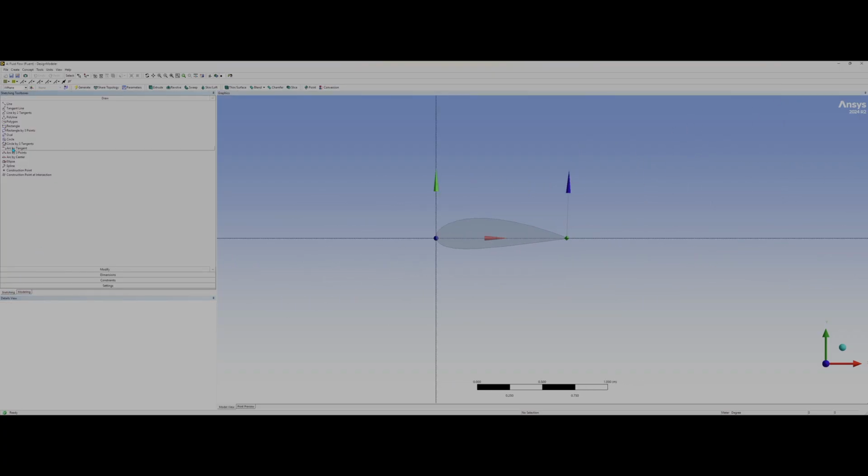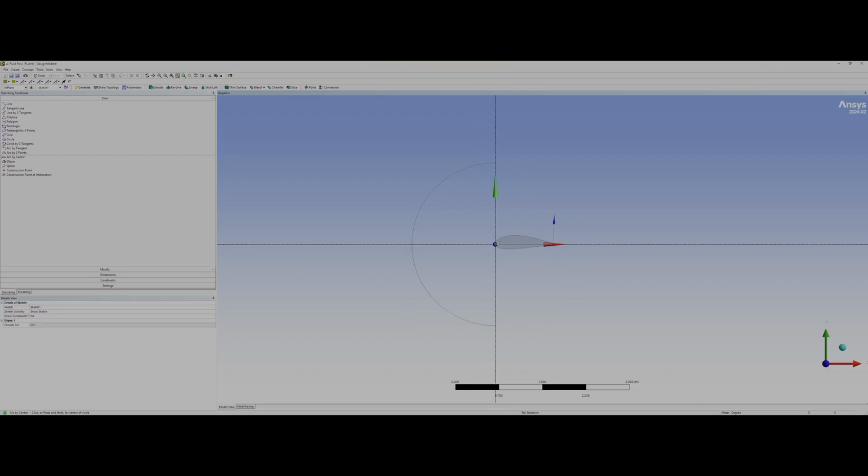Next thing after that, we have to make our domain. Go to sketch. And in sketch, you do arc by center. And we're going to make two of them. All right. One smaller one and one larger one. Right here, right here. Now that is done, just create lines going straight up. Here, here, here. And you're just essentially going to just close these.